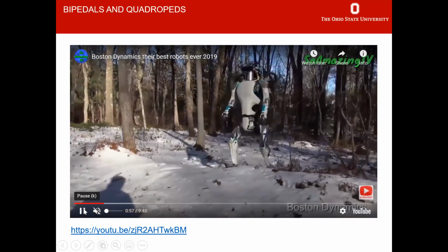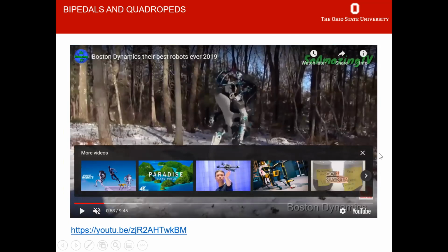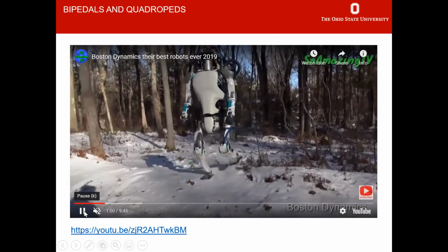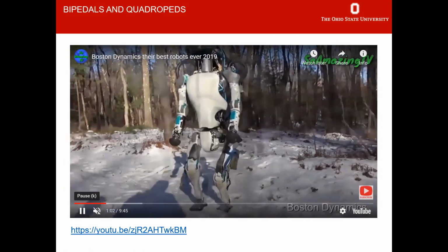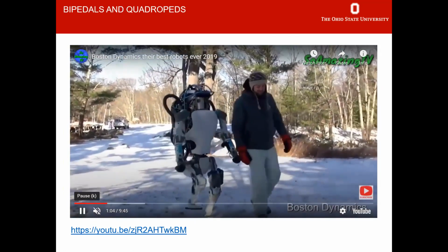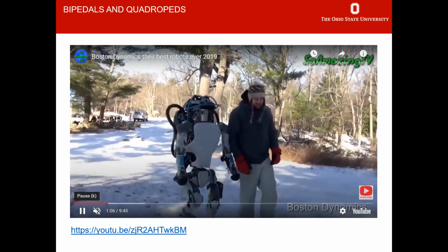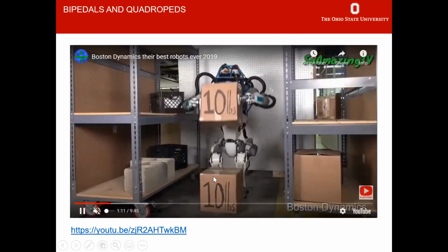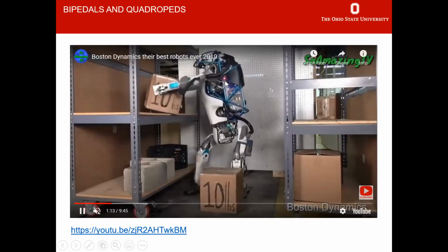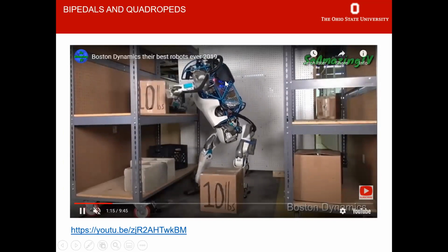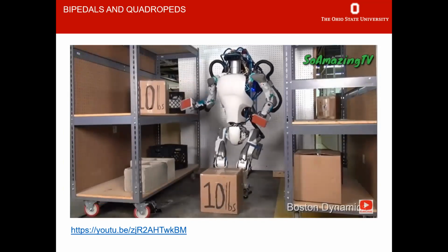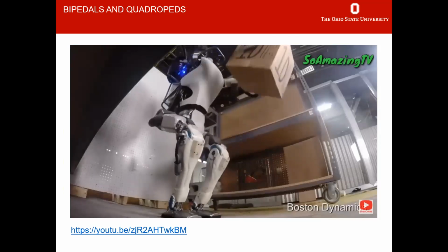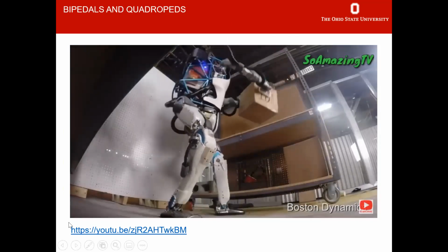So these are challenging tasks, and yeah, it's about to fall down. Let's see if it falls down. It didn't, it did better than me, okay? Obviously, so that was a disturbance, okay? So it has to do very nice disturbance rejection. This is, when you put the 10 pounds, that's a change in your operating parameters. Your model is all of a sudden changing. When you add that extra mass, your model is changing. Your controllers need to work with the new model also.